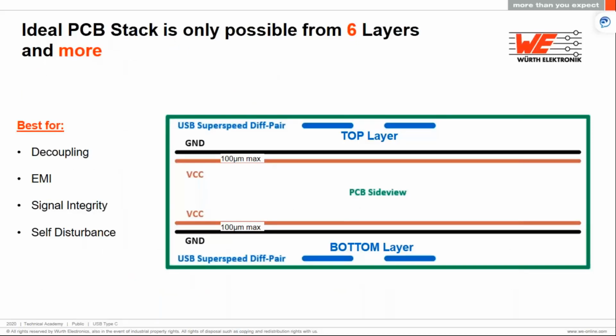So for example, if you have a PCB where you have to route high-speed signals on both the top and the bottom layers, it could be anything such as USB or HDMI or even 10 gigabit Ethernet. If we have any of these high speeds on both sides of the PCB, we need at least 6 layers. Only with 6 layers is it guaranteed that every data signal has a designed ground return path at the same distance to guarantee the same impedance.